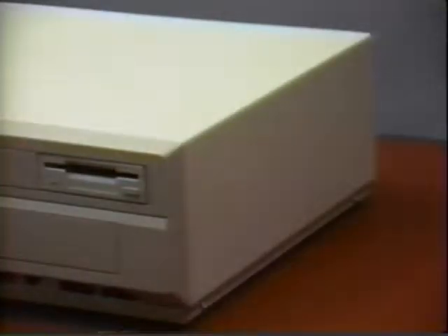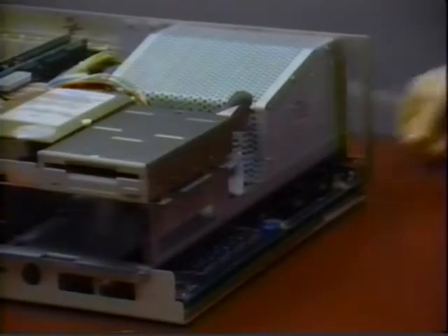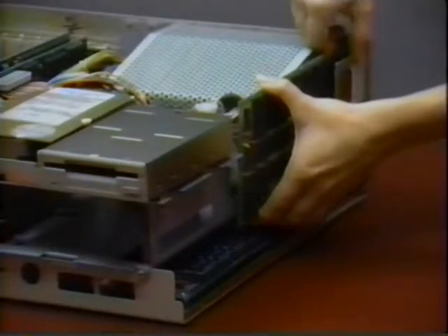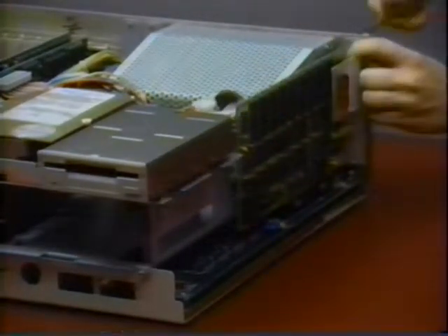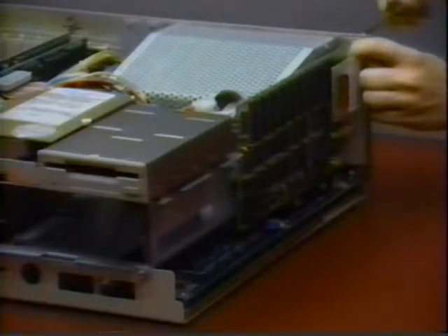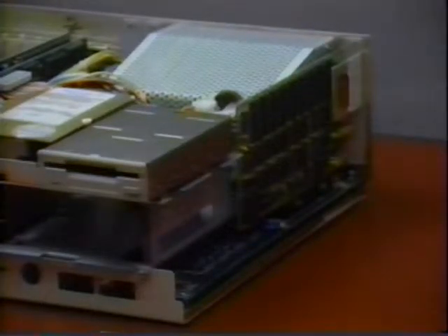The flicker fixer slides into the video slot beside the power supply. Remove the two screws securing the video slot cover and gently insert the flicker fixer, then tighten with the supplied screws. The flicker fixer outputs a higher frequency video signal than the standard Amiga video port, and therefore requires a multiscanning or VGA compatible monitor.